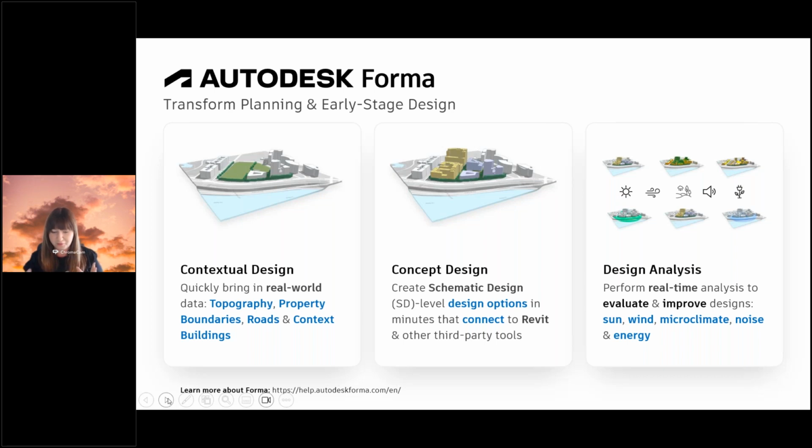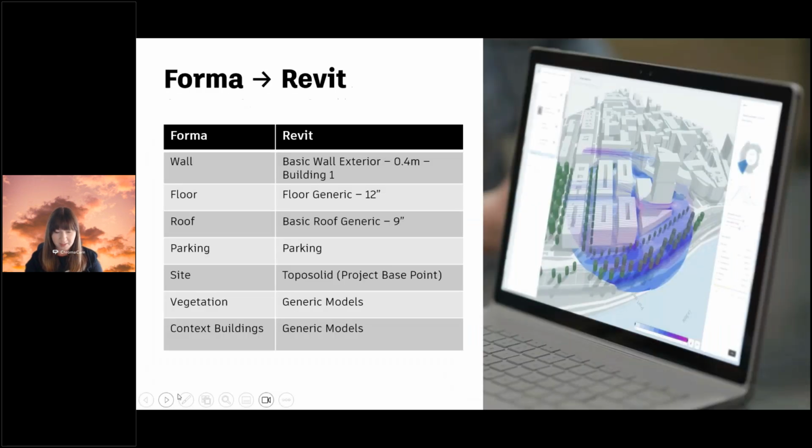It's just much more of a free-form tool. And then lastly, I will be able to show us how it transitions into Revit, if we have time at the end. I just wanted to share a quick chart: everything we do in Forma will be thin-lined, so it doesn't have thickness. But when we transition it into Revit, it will take on thickness.